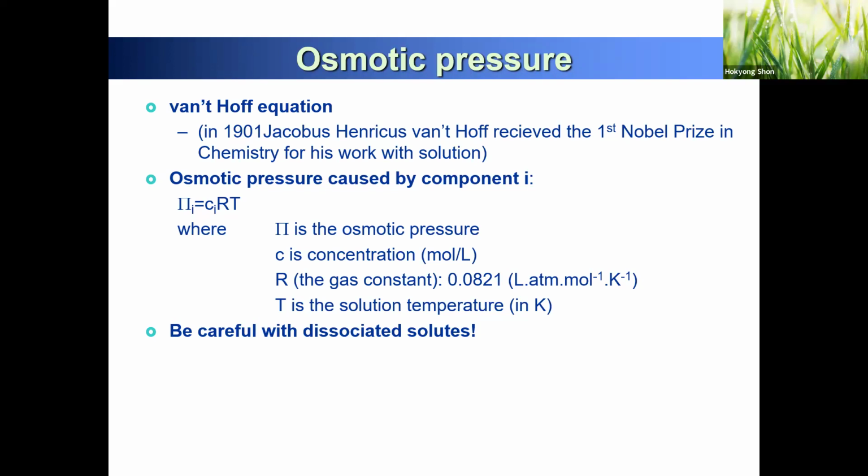When you have a detailed concentration of the specific ions, you can put them into the water quality input, and the software will automatically calculate osmotic pressure. You don't have to calculate using this equation for sodium and its pressure, and chloride and its pressure, one by one, because the software will give you the overall osmotic pressure data.